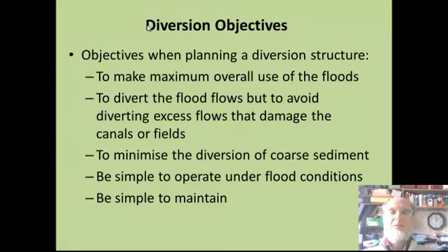Now, we'll talk about diversion objectives. So our objectives when planning a diversion structure are to make maximum use of the floods, to divert the floods but to avoid diverting excess flows that can damage the canals or fields, to minimize the diversion of coarse sediment, to be simple to operate under flood conditions, and be simple to maintain.